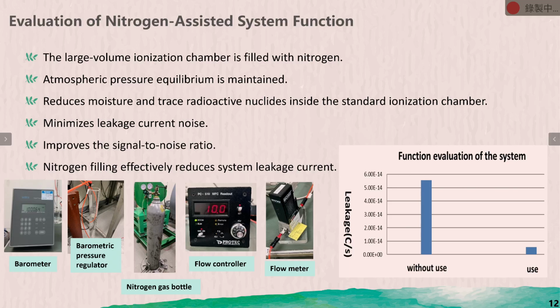The second thing I want to ask: how long does it take to fill such a large ion chamber with nitrogen gas? In this picture, we can see that we use 10 SCCM, the unit for STP, standard temperature and pressure.